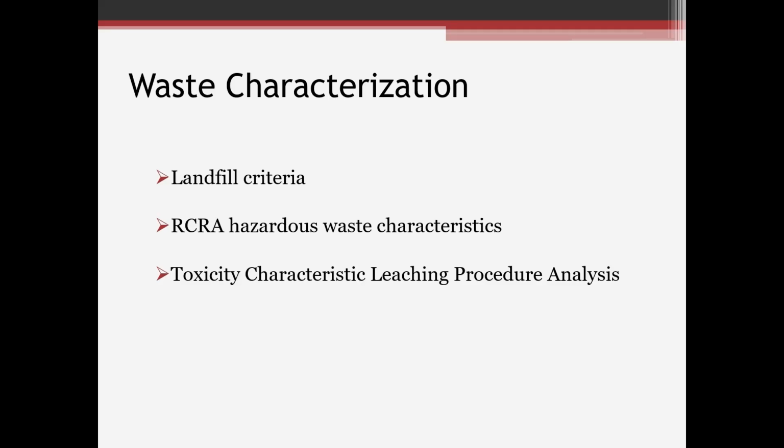But each landfill is going to have their own set of criteria that you will have to comply with if you want to take waste there, or they won't accept it. So it's good to know what the landfill wants or needs. With this, we're looking at recording hazardous waste characteristics, which I went over, those 4 characteristics, and then the toxicity characteristic leaching procedure analysis. So we're looking at, if we were to put a material in a landfill situation, what's going to leach out from that material. That TCLP analysis gives you that sort of assessment.